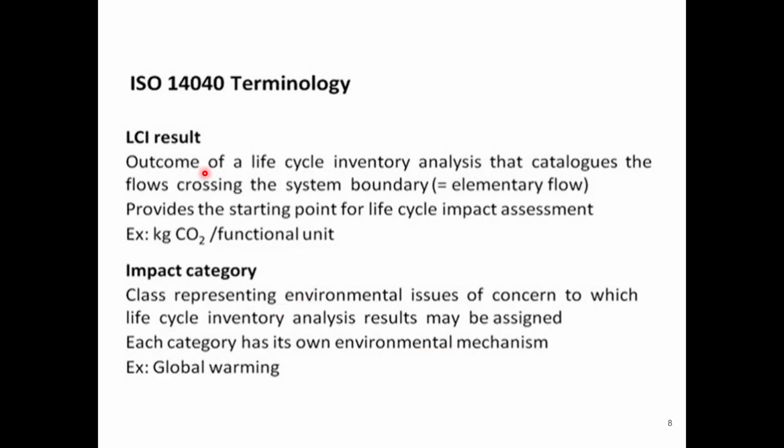What is the definition of LCI result? It is the outcome of a life cycle inventory analysis that catalogs the flows crossing the system boundary, and that is equal to the elementary flow, because that is the flow coming into and going out from the system. That is the system boundary. It provides the starting point for life cycle impact assessment. Example: kg CO2 per functional unit.